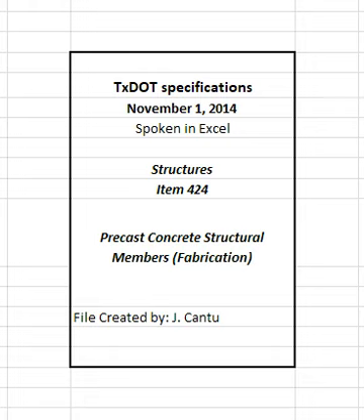Begin curing after the finishing operation, before the formation of plastic shrinkage cracks, and as soon as damage to the surface finish will not occur. Provide fog spray or an evaporation retardant after finishing and before curing if needed to prevent plastic shrinkage cracks. Apply fog spray or evaporation retardant in accordance with Section 424.4.2.5.2, placing concrete in hot weather.